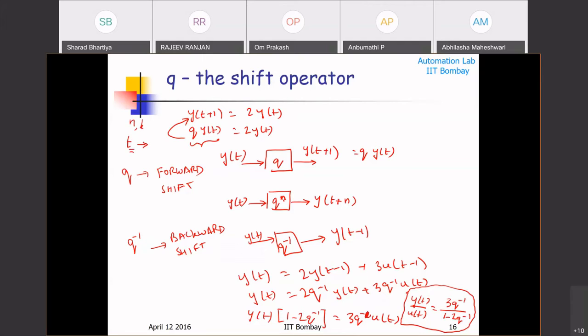Okay. And you will see when we use the toolbox that they always use t in the system identification literature. So this that I have written over here now is an example of a time series model. It is telling you how y of t is changing with u of t. And if you would like to see the more obvious way of looking at it, it was this: y of t is equal to 2 y of t minus 1 plus 3u evaluated at t minus 1.